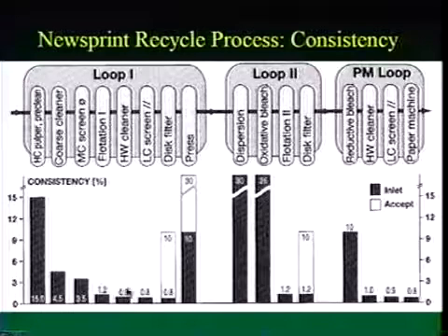So we've done all these three operations together because we're at a low consistency state, and that's useful for all three of these. So we don't want to be thickening and then diluting and thickening and diluting if we don't have to. Now at that point, after we do our low consistency screening, we are going to start to thicken.